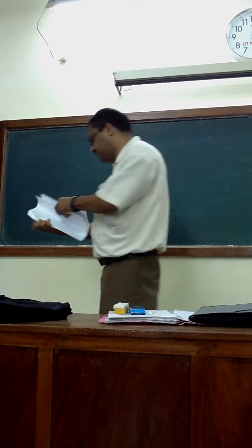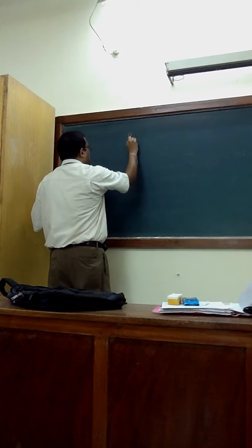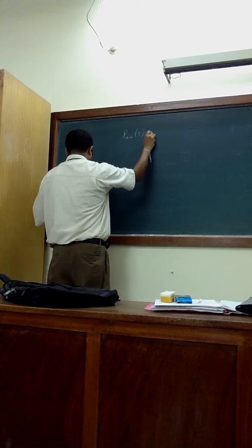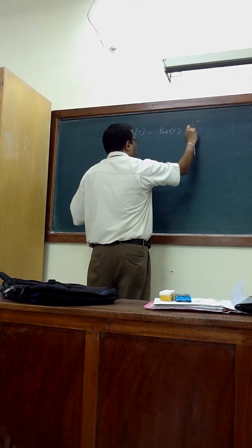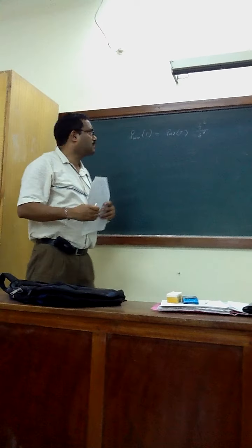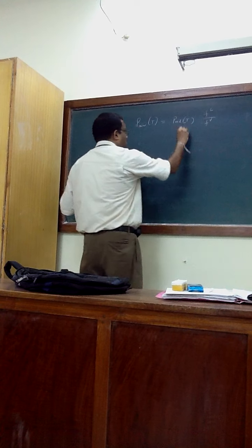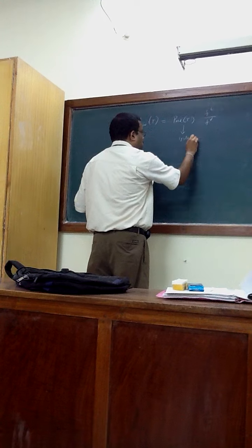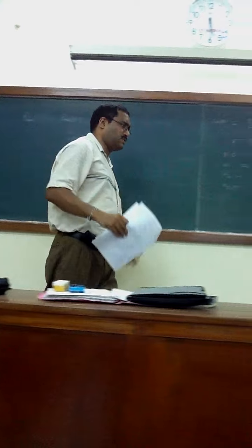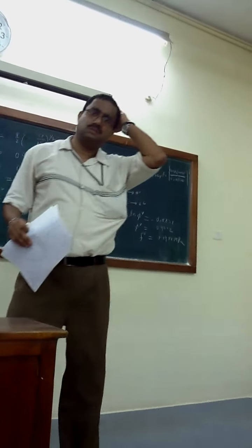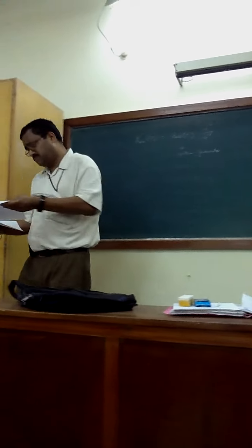Okay. So our algorithm says what? If we look at our algorithm, P new equals P old times fL by fV. This was the system pressure for the initial first iteration, which is 0.215 megapascal. You are seeing that assuming equilibrium at this system pressure will not be correct. You have seen it. So what is your P new then? How much is P new?